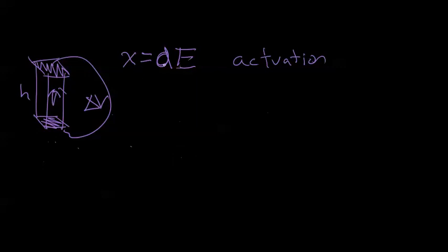So we have the strain, the piezoelectric D constant, or the charge constant, multiplied by the electric field. And this is the same exact constant which we just saw earlier in this equation. It's kind of interesting that these completely couple, and the same property is used for both cases. Now, in actual terms, we want to look at real parameters.